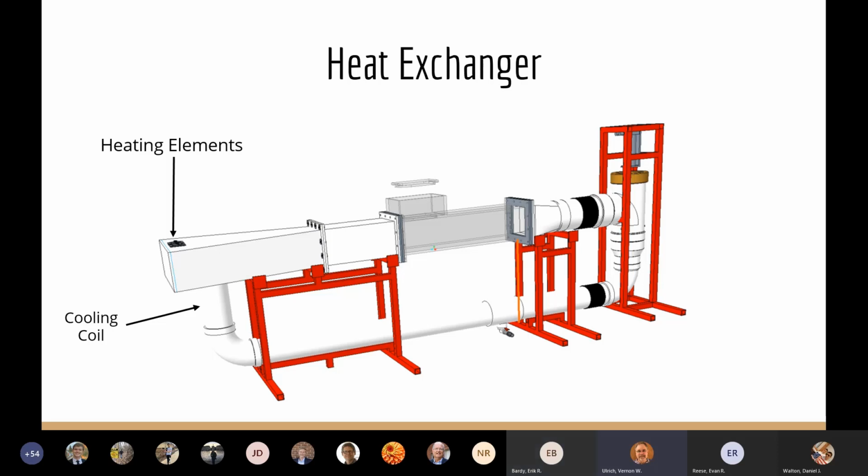Anyway, I was looking at the frame there and thinking that as you weld that together, the bottom pieces are likely to warp some in one direction. Have you considered adding anything to it for leveling the three sections in order to get the alignment that you want?